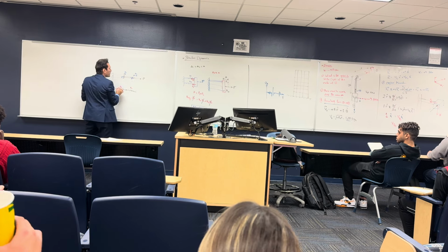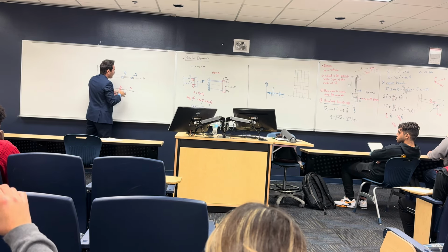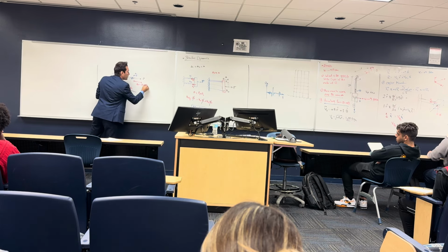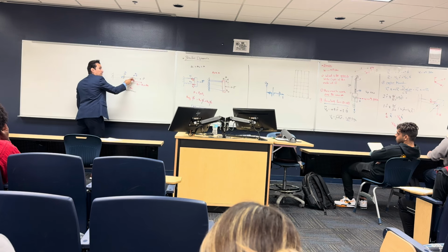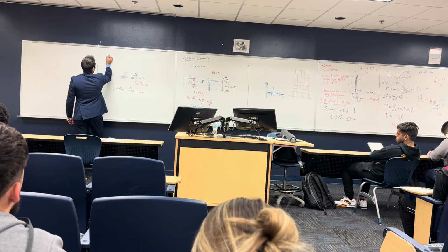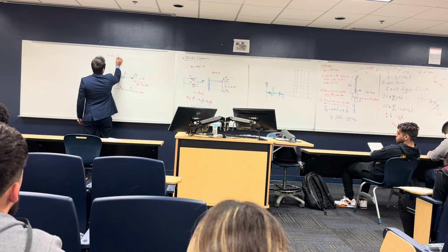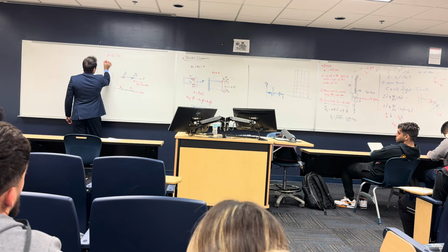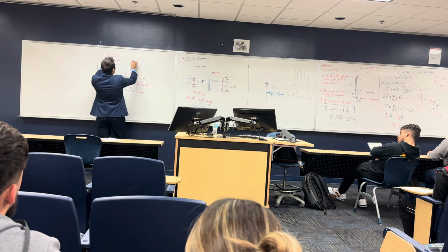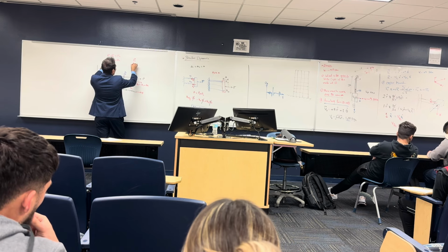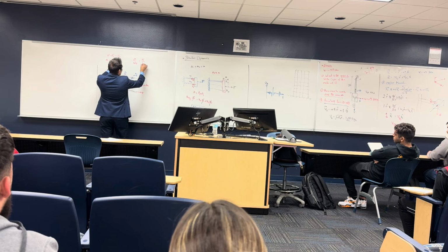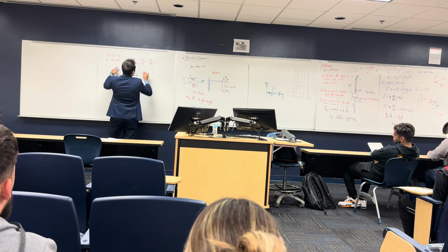Okay? And the final displacement of the whole system is going to be final delta, which is delta 1 plus delta 2. The delta that happens here plus the delta that happens here. This is what is going to happen. So what we have here, we have that P is equal to P1 equal to P2, right? And I have that delta is equal to delta 1 plus delta 2. I can substitute here by delta. Delta is equal to the force P over the K equivalent of the system. This one has the force P1 over K1 plus P2 over K2.